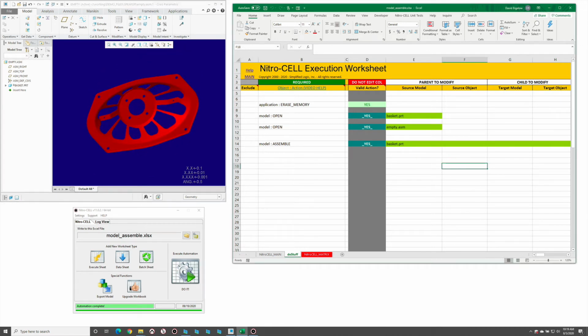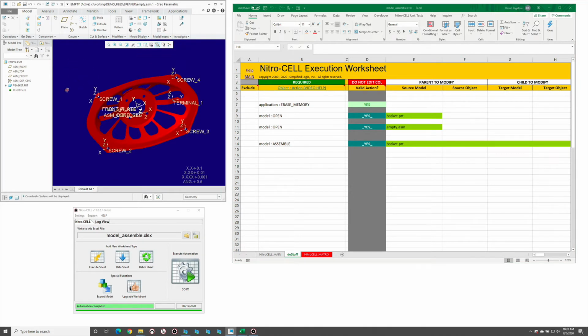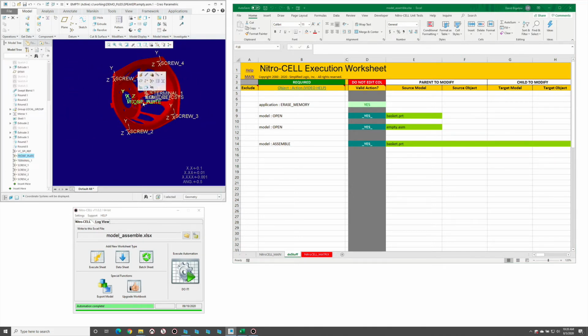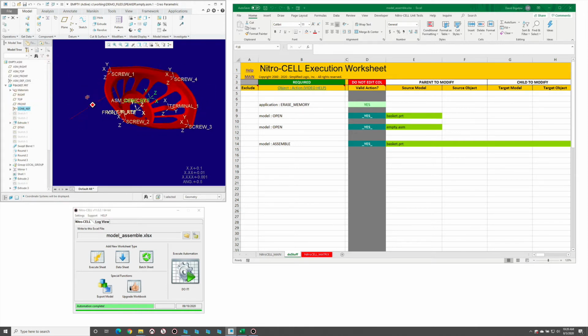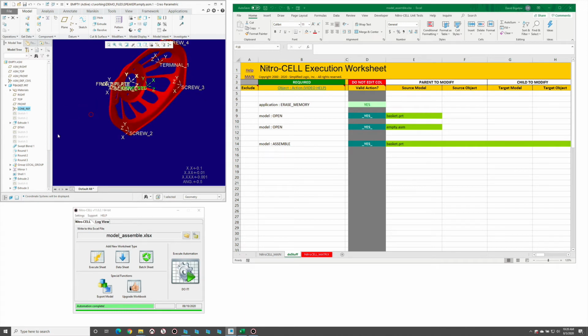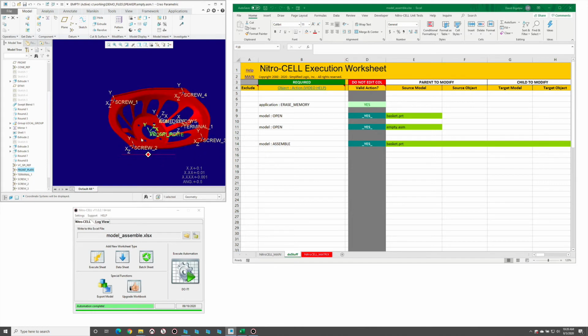If we want to constrain that, all we have to do is come in and turn on our coordinate system references here. And let's take a look at what this one is. So that's our front plate reference. What else do we have? Where's this cone reference at? I thought I saw. Yeah, cone reference. So cones is one location, but let's use the front plate reference because we'll use that as the foundation for where we place the rest of the stuff. So we'll type in the name of that coordinate system, which is front plate.